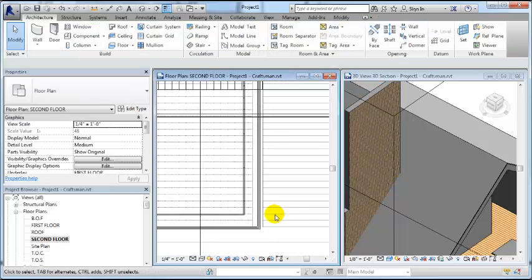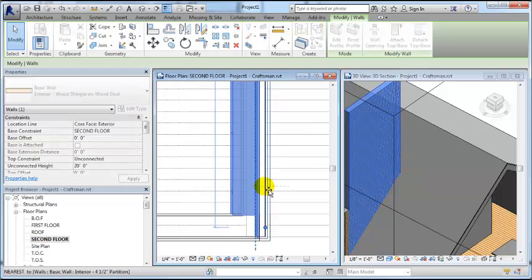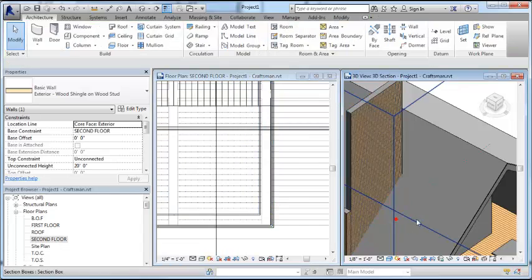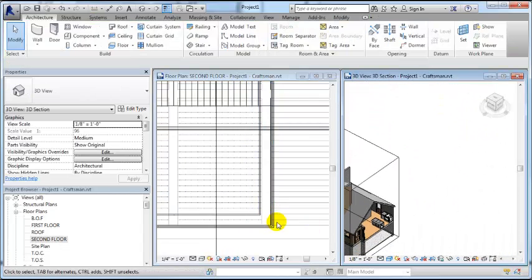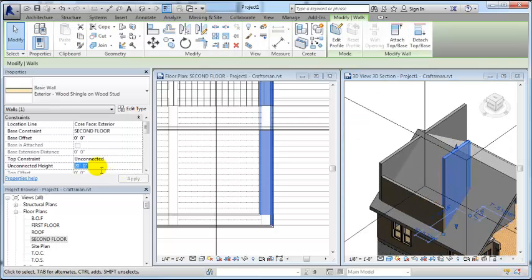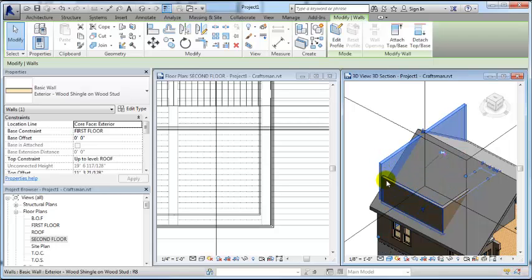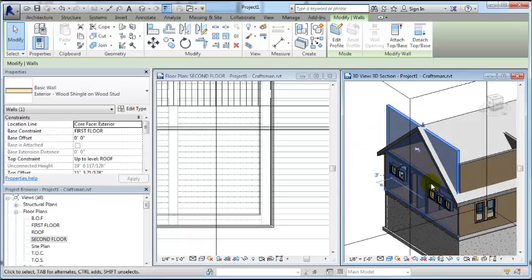As I said, we're gonna really analyze this and make sure that we place these walls in exactly the right spot so that they match up with what we need them to match up structurally. So that wall too I'm going to set to 7 feet. And this wall I can't set to 7 feet because then that will make it 7 feet from this floor, not this one.